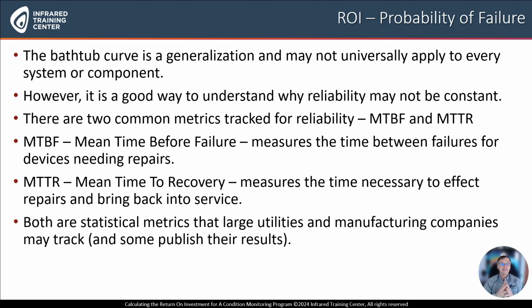Now, MTBF means the mean time between failures, and that measures the average time between failures for devices needing repairs. And you can find some data online as to the typical MTBF for a motor or for a cable or for a pump, but they might not be for your application. The MTTR is the mean time to recovery. That measures the time necessary to get something repaired and bring it back into service. And this might be something that an individual program might want to start to track, particularly if you're just starting up a program like at a brand new facility.